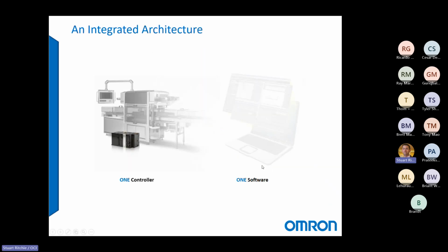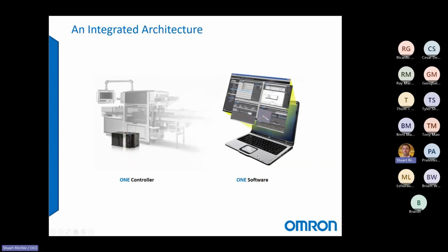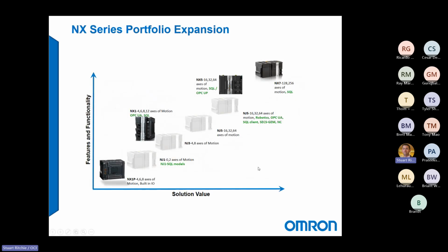But Sysmac is a truly integrated architecture. So our philosophy is we have one piece of software, we have one project file, we have one controller, although you may have many, but we have one connection that lets you access and configure all of that. And most importantly, everything in your Sysmac system is going to be saved on one project file. So you could have your safety CPU, your drive parameters, your multiple PLCs, multiple HMIs, that kind of thing. Makes it easy to manage, especially when it comes to change management.